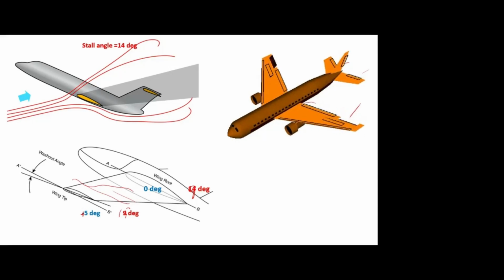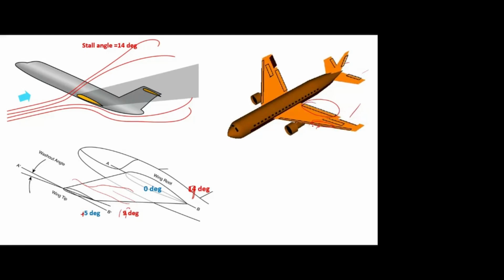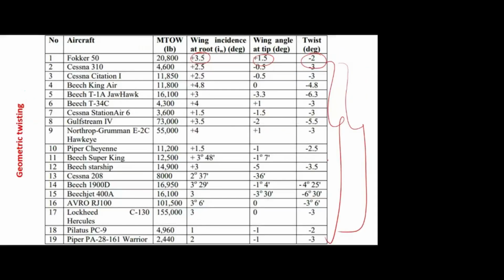But this flap, here you can see one rectangular portion, right? That is the leading edge slat. These things are all high lift devices. They are to increase the lift. Using them, we cannot control the aircraft. They are only to increase the lift, so they are called high lift devices. So don't confuse control surfaces with high lift devices.